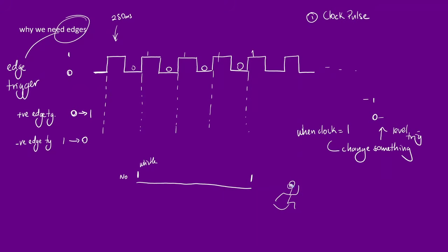after the finish line. So most things you handle in life and in electronics are going to be edge triggered because it makes more sense, it's better. You get better electronics, smarter electronics, faster electronics when you deal with things that way. Okay, so I've covered triggering, why we need the certain types of triggering, the active triggering and the positive edge trigger and the negative edge trigger. So the last thing we're now going to handle is the toggle.